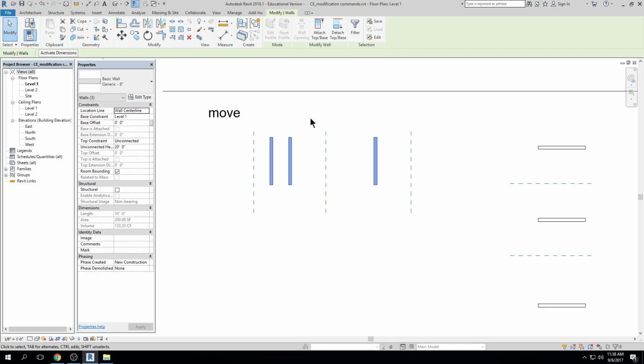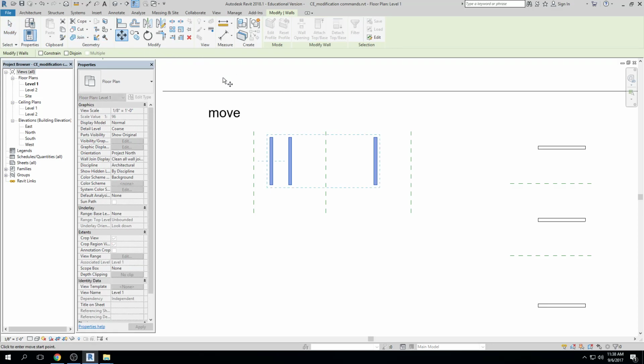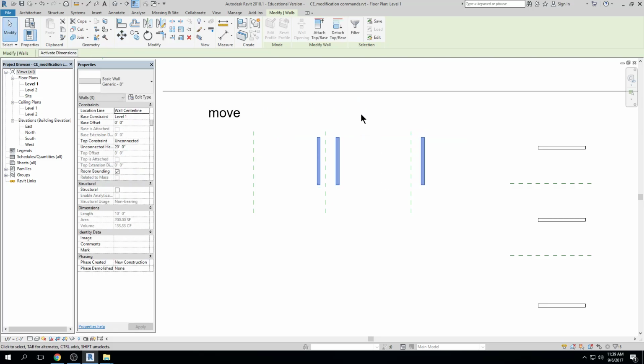Everything grays out and you can't move, but there's a little box on your screen with an X, click the X. Okay, so I've selected everything. Now I'm going to click on move. Click, I establish a base point. Click, move in the direction I want to go, and I can either click or type a dimension. 10, enter. And you remember 10 implies 10 feet in Revit, right? As opposed to 10 inches, which is the default unit in AutoCAD.